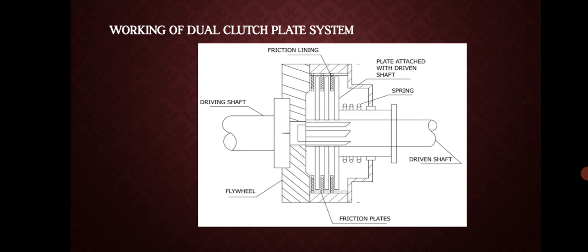In between the two clutch plates, an intermediate plate is provided. Normally, three release levers serve the purpose of disengaging the clutch plate. However, some of the tractors have 6 release levers, 3 each for main drive and the PTO drive.